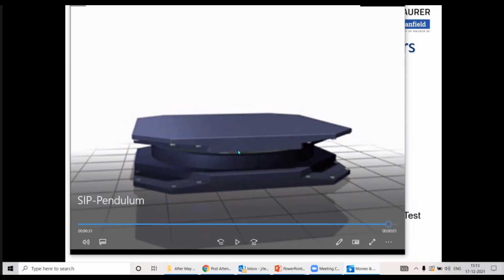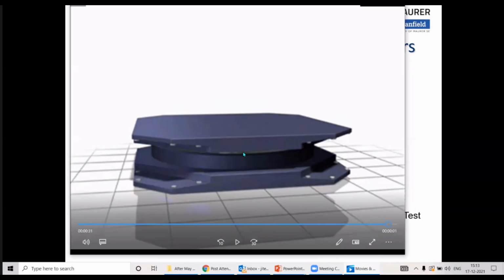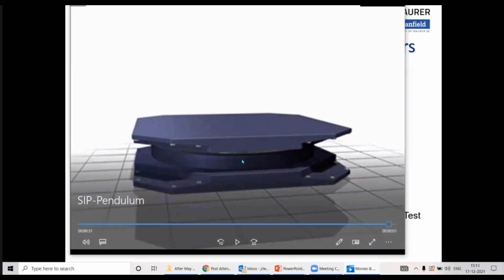And then the recentering is automatically achieved because when it is going at the periphery or towards the corners, it is going up and there is a dead load on top of these bearings of the structure. So when the earthquake is gone, by virtue of the dead load itself, gravity loads, it comes at the center. So the recentering is automatically achieved.